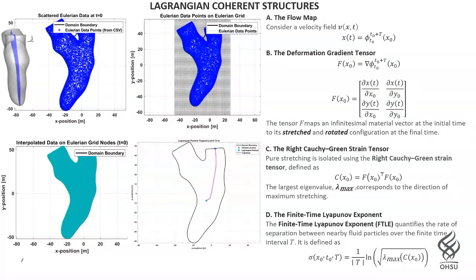First, I put a Z-plane on the 3D geometry, and then I extracted all the grid points and the velocity information onto that plane. If you look at that one, they are not fully aligned because I used tetrahedral meshes. This is not a perfect structured mesh. So I interpolated that result and generated a grid.